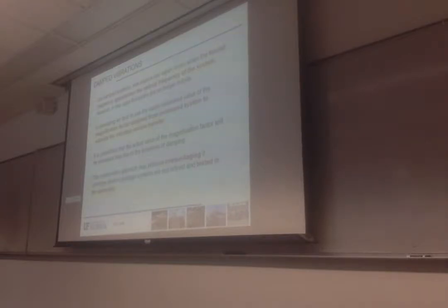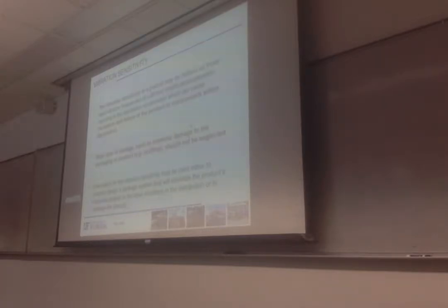So that means that you should always design a package, try to design the best you can, taking into account vibration, shocks, the material available, and all these things. Go in the lab and test it. Then, based on the results you get in the lab, that's where you need to go back, discuss this, remodify, and retest again.